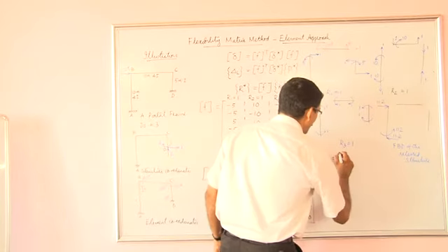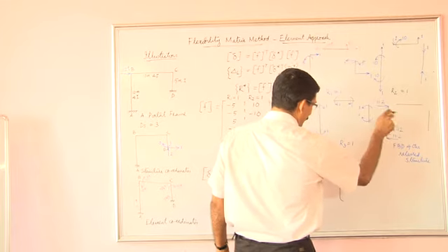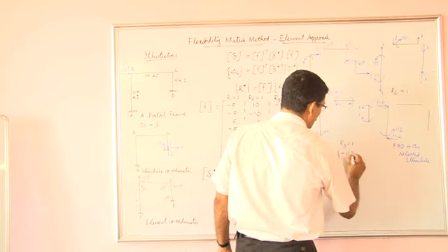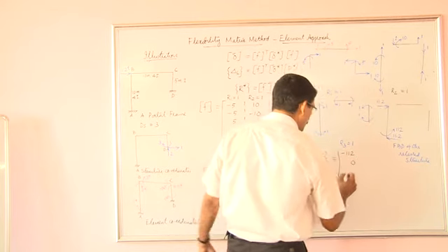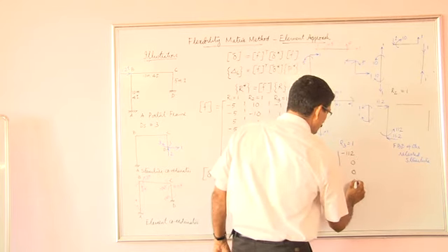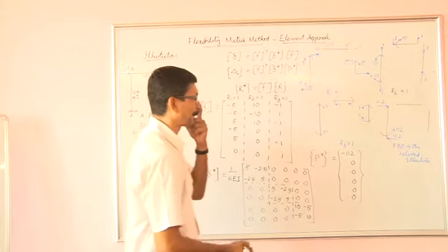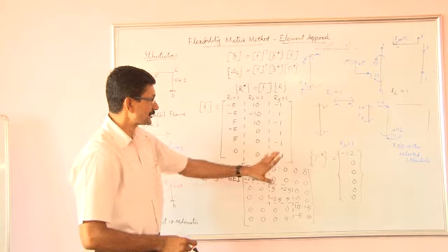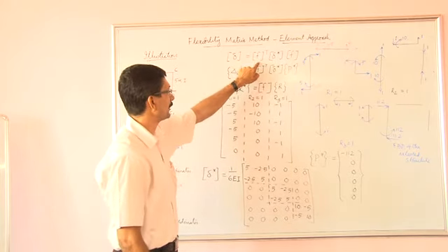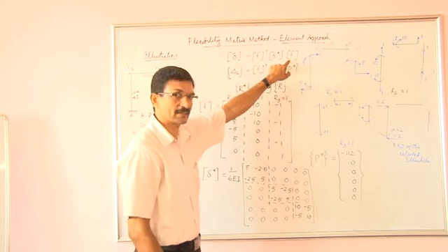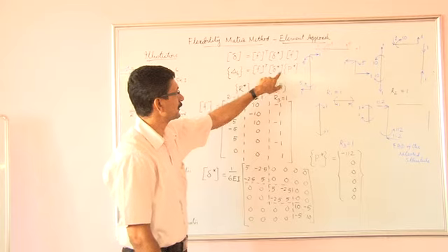The P star will contain 112 anti-clockwise, so minus 112 is the first element, then there is nothing, so 0 corresponding to 2 star, 3 star, 4 star, 5 star and 6 star. That is it. So everything is in place. We can now construct this delta matrix by transposing F multiplying with delta star and further F, and develop delta L vector as F transpose delta star P star.